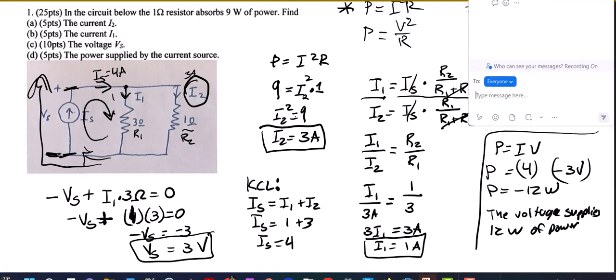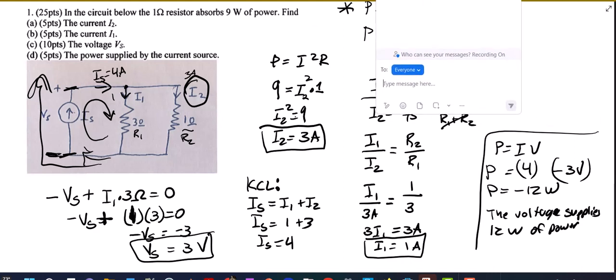I have a question. Sure. So to find the voltage source, why couldn't you just do a source transformation? So like IS times 3 ohms, and then... Okay, because a source transformation allows you to solve the rest of the circuit, but it transforms the very thing that you're working on, so you can't use it to find the thing that you're transforming.